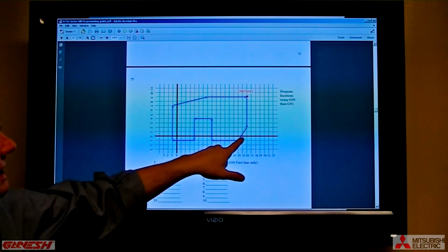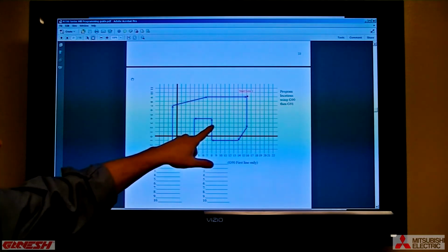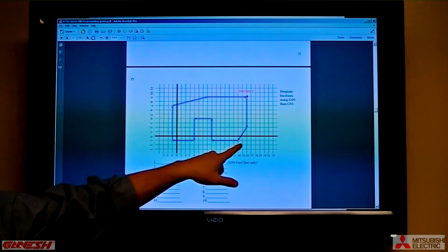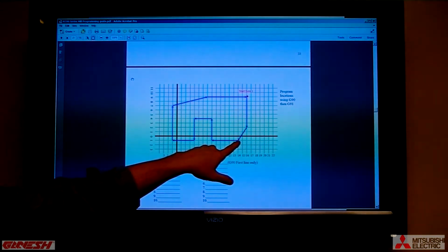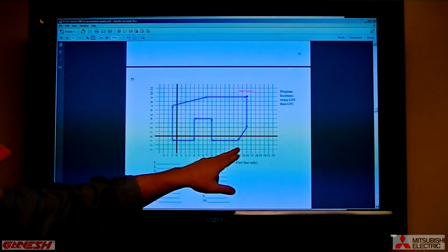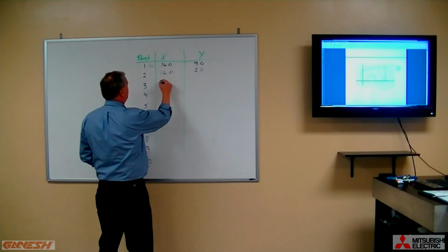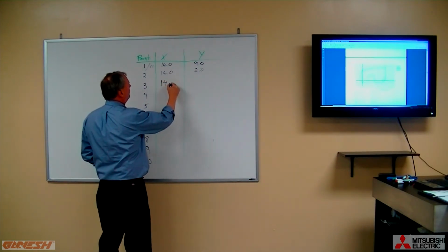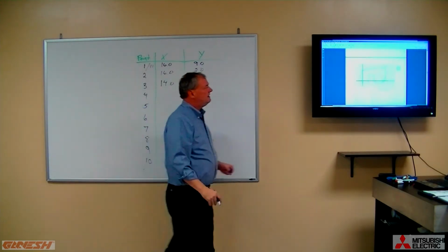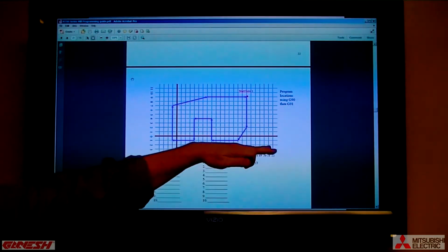All we're doing is saying point to point to point to point, and then the cutter will, in this example, follow a straight line path. So even though this is at an angle, it's just looking to get to the endpoints. And so it goes to x14, y minus 1 would be the next correct answer. So that's x's value of 14. And now we're below the y-axis. So anything down here is the x plus y minus quadrant.